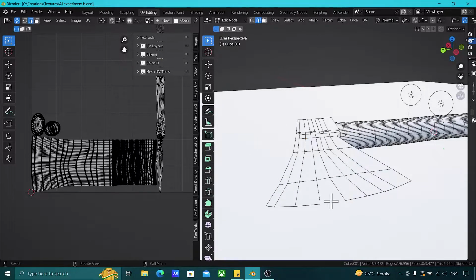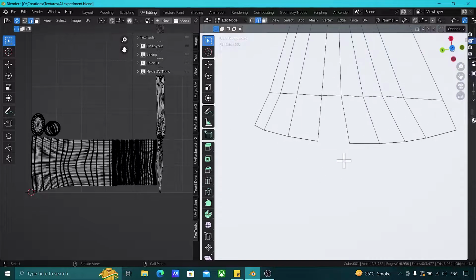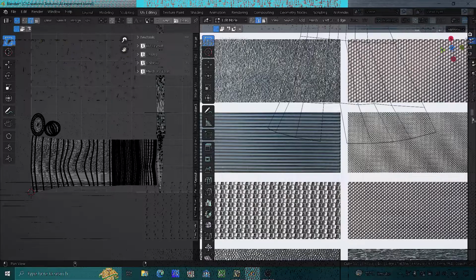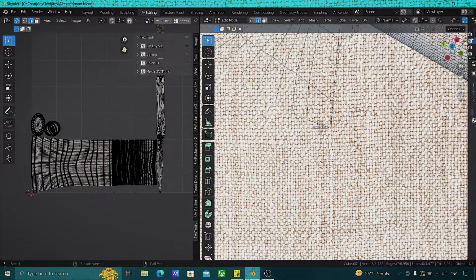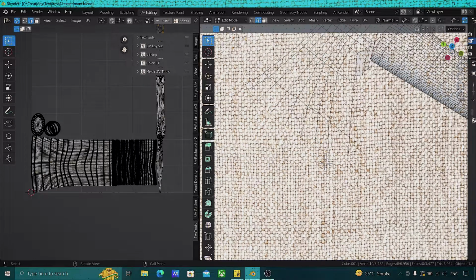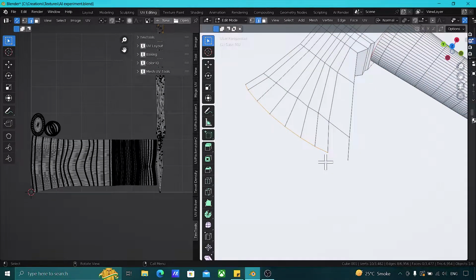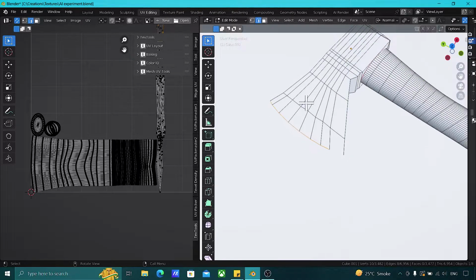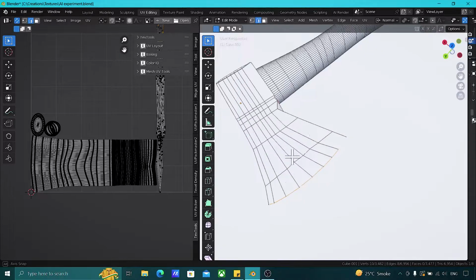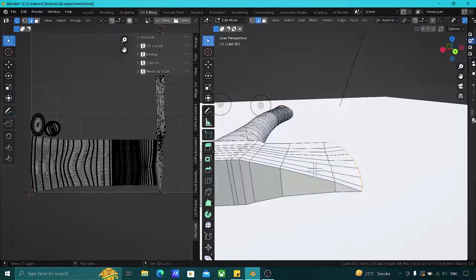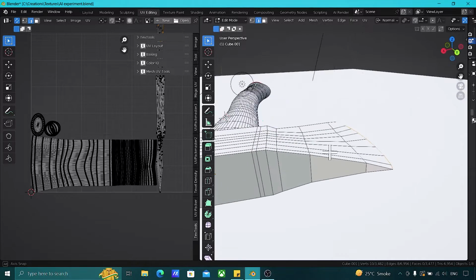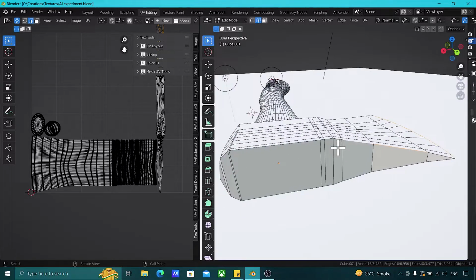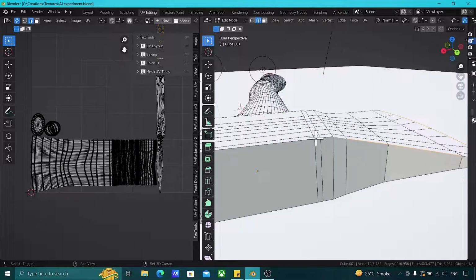All right, so we can simply mark it as a seam, because metal is always a good object to unwrap, because it's not that irritating to be honest. Wood and fabric are quite precarious when we unwrap those surfaces, because they can simply mess up things, and their seams are quite visible if you don't do it properly. But in case of metal, in case of substances that are not very texture oriented, it's fine to place the seams at the right spot without caring about the seams, unless it has some kind of noise or grain that is visible. It's completely okay.